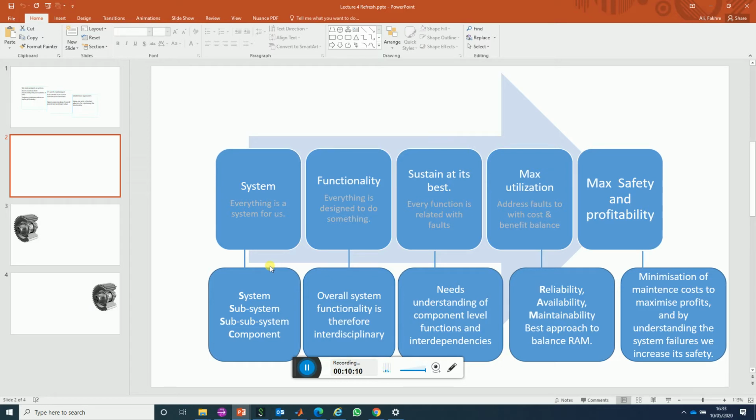Now, the reason why the engine may suffer lack of enough supply of fuel could be related to, for example, blockage of the filter. It could be due to the malfunction of the valve, which can be related to electrical failure. So if the valve is electrically powered, it may be that a circuit failure can lead to malfunction of the valve, and the valve gets stuck at one position, and so therefore we can't have enough orifice through the duct to supply enough mass flow to the engine.